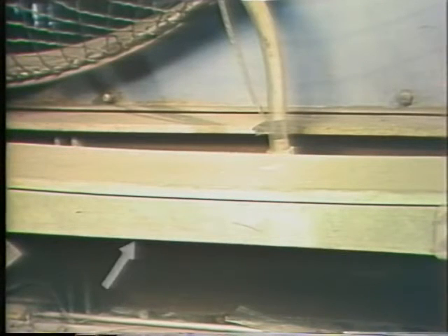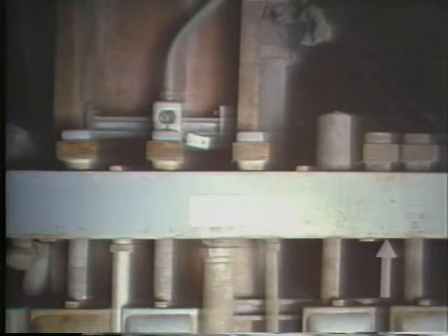In the next two segments, we're going to talk about raceway diagrams. Raceways are any designed structure that cables and conductors follow in a plant. They can be a pipe-type design, which is frequently called conduit, or they can be racks on a wall or ceiling that conductors are laid in. Raceways can be long metal boxes called ducts, or they can be metal troughs that are frequently called trays.